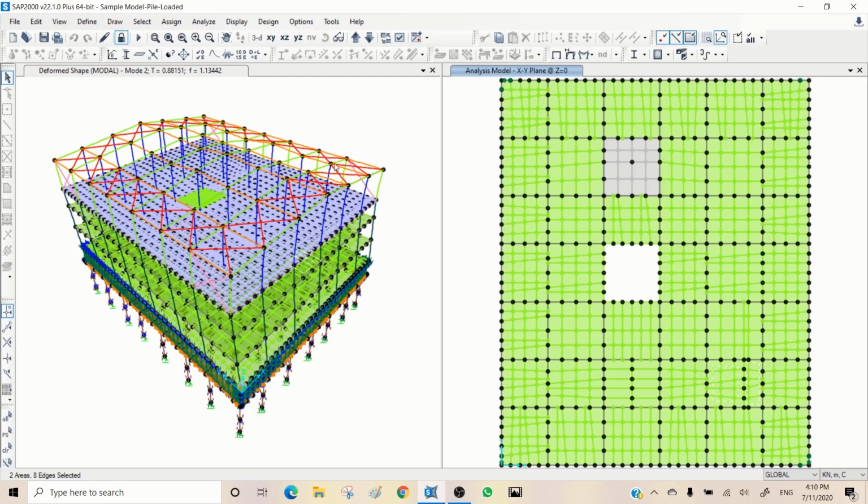If you have some braces, you don't want to connect them together, you need to exclude them from your selection. The next stage is selecting all joints and also all shells and auto mesh the shell, but you need to see which option is suitable for you. And the last stage is selecting all vertical and horizontal shells and do edge constraint.